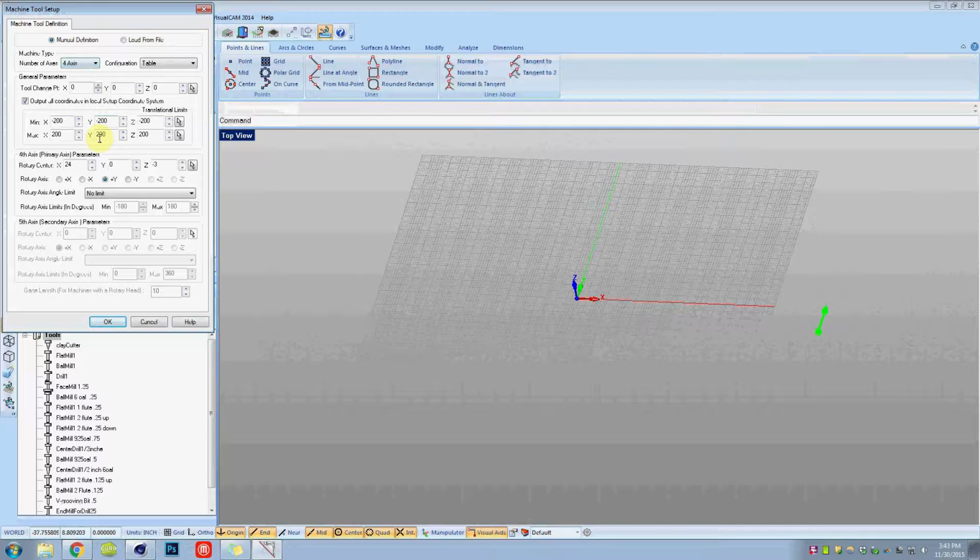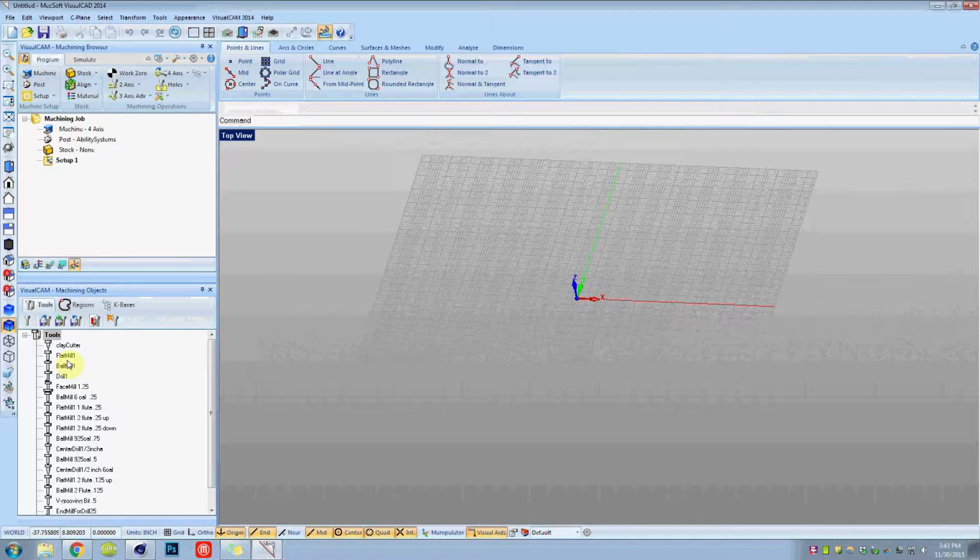If you're going to be rotating your part, if you're going to be flipping it over for a double-sided mill, which we will be doing, you want to set your 4th axis parameters, which is the Rotary Center, so where it imagines the piece is spinning. In this case, this is half the x distance, which remember was 48. This is 24. None of the y distance, because we want it to rotate along the end, and then half the z, remember, which is -6 because it was below the surface. This is -3.